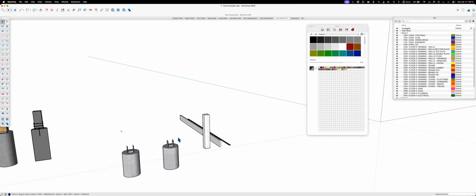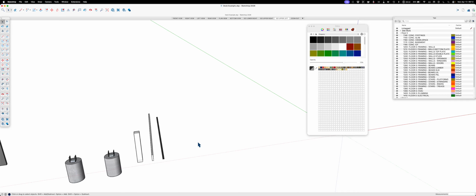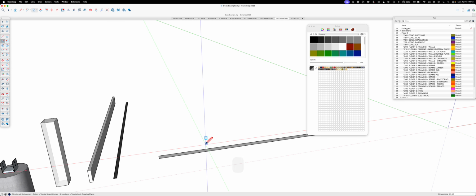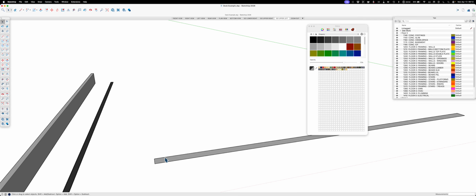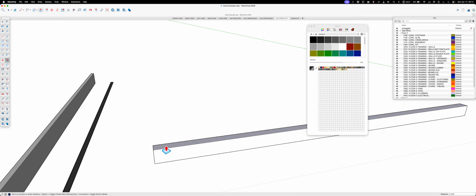You have your posts. We need to have a couple beams. So we'll do a drop beam that's a 4x. Some places in the world don't even have that. We have 4x lumber up here, so you don't have to double 2x anything and hope for the best. Let's do, which way is this going? Let's go 12 feet, comma, 3.5, enter. And since it's a small deck, we'll come up 9.25.